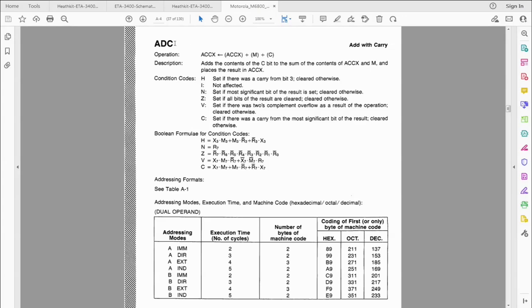Well, for the first add, you would manually use the clear carry instruction to make sure, because when you are adding something to the lowest byte, there is no carry from a previous instruction. And you're basically going to do 4 adds, but for the 3 subsequent add operations, you will just use the carry that was generated from the previous one. And your result will be a proper multi-byte add.